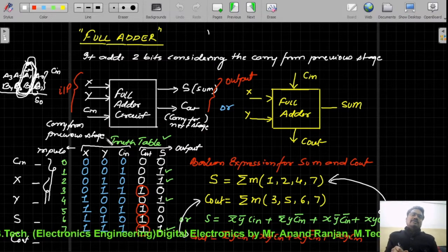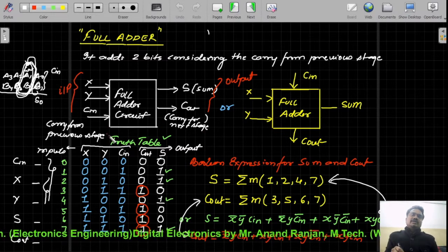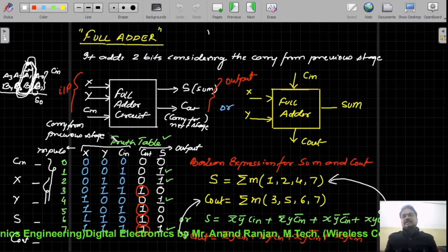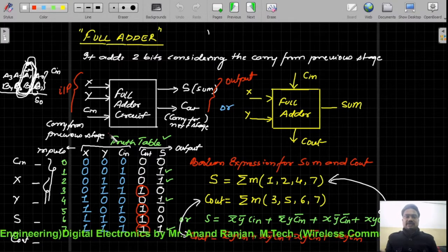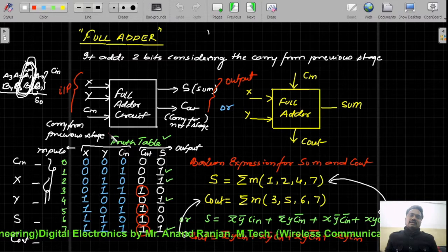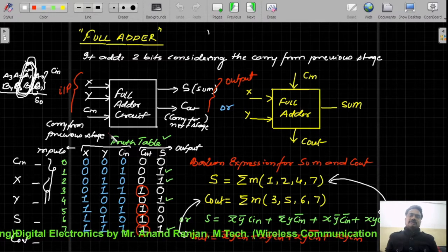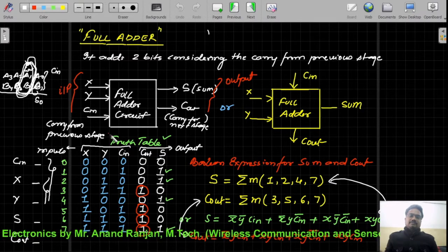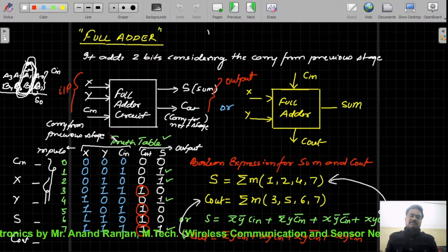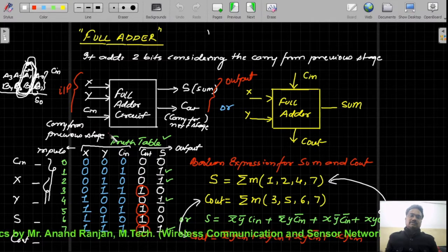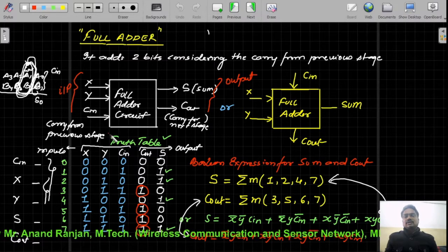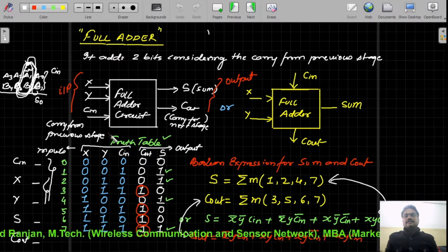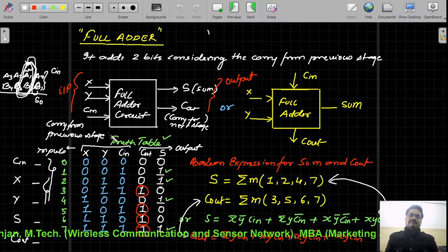Again, regarding the overall functionality, we have said that there are 4 standard procedures to analyze any combinational circuit. First you identify your inputs and outputs, then you write the truth table based on the input and output variables, and finally you write the Boolean expression for the output, and if possible reduce it using the Karnaugh map or Boolean algebra concepts. Finally, the reduced Boolean expressions are implemented using the basic logic gates.